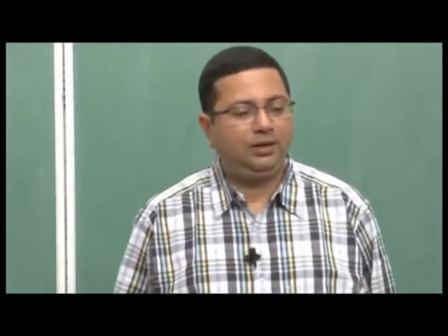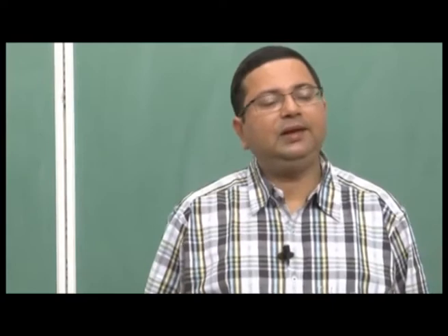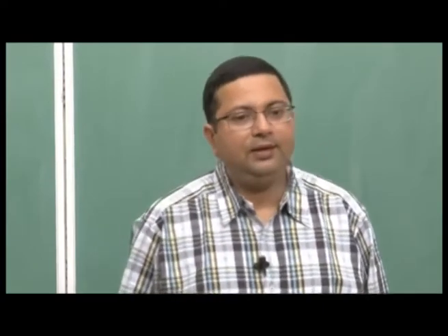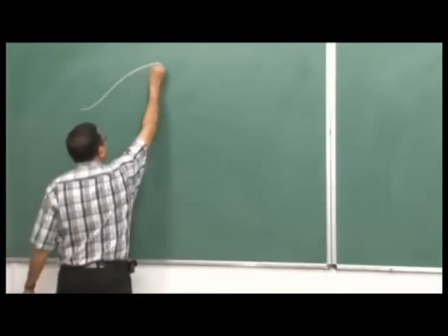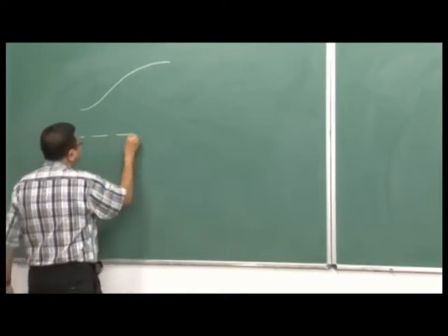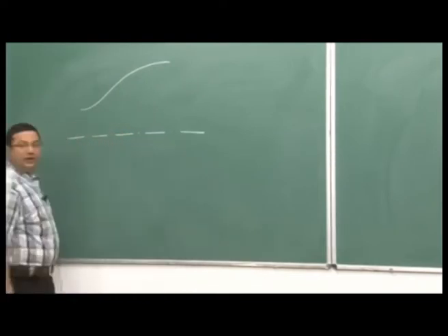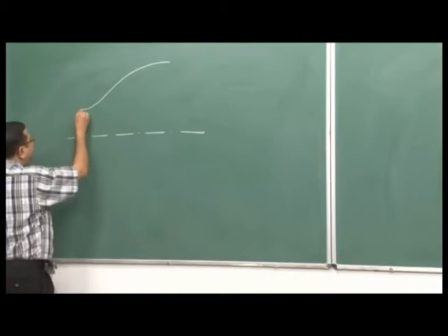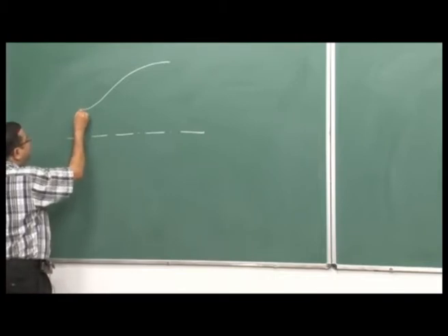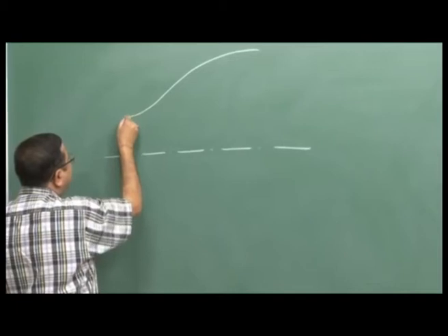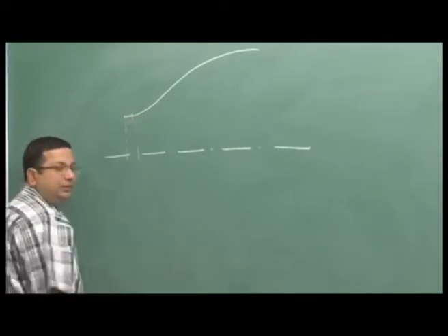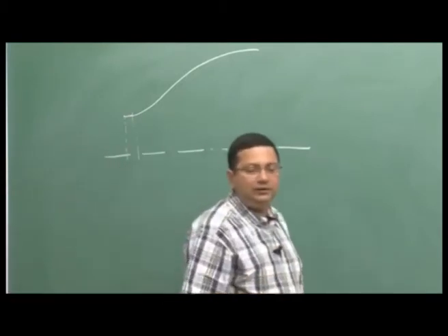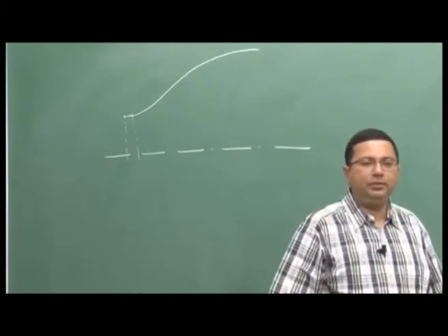Good morning. Till the last class we have been discussing the shaped nozzle. In the last class we talked about how to design a shaped nozzle using the method of characteristics. First of all, the initial condition we choose slightly ahead of the throat, then the initial curvature is fixed, rather we choose that initial curvature so that we get the required Mach number.